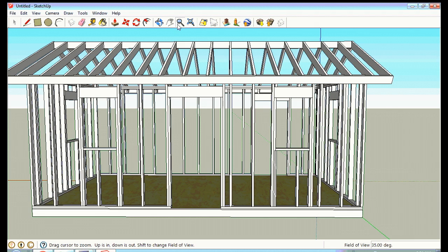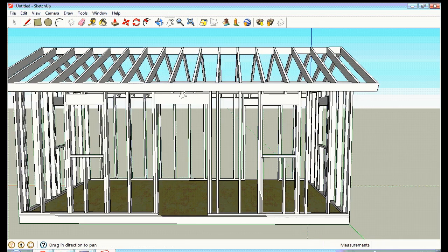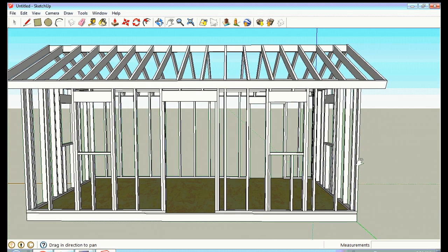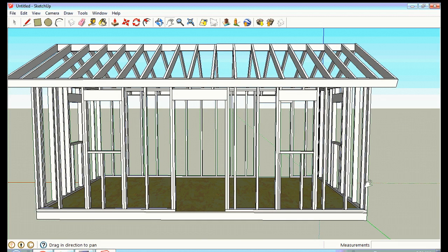Now, corners of a house have always been kind of a tricky thing because you need to put in studs that will give you something to nail your drywall on the inside to, but also give the corners of the house, which generally hold most of the weight of the roof, good, strong, sturdy corners. You need something to be able to nail your wall 2x4s to, and also to attach your drywall to.